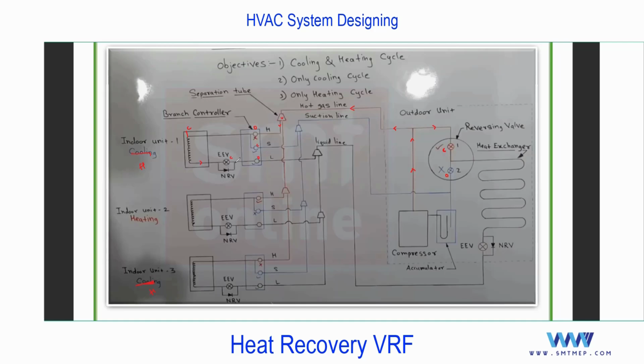It will pass through this bypass line with the NRV, then out. And this also from the other ones. And this, now it will enter the electronic expansion valve. It will pass through this, and this will become the evaporator. And after this, you see, since this valve is open and this is closed, the refrigerant will pass through this and enter the accumulator, then the compressor. This is for heating. And what we are learning is a concept. In actual practice, this can be achieved with the complete control system. Okay, with precise control, this is not that easy.